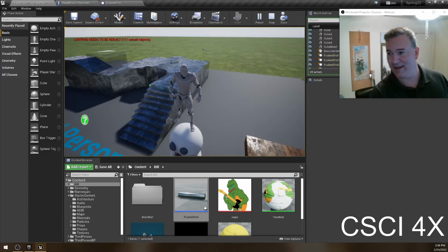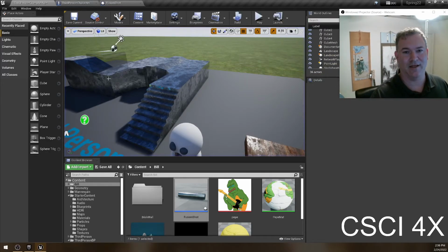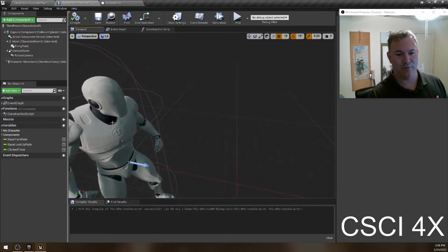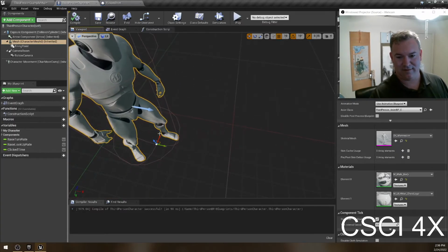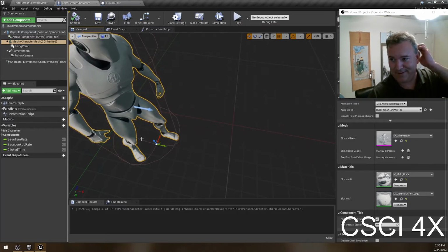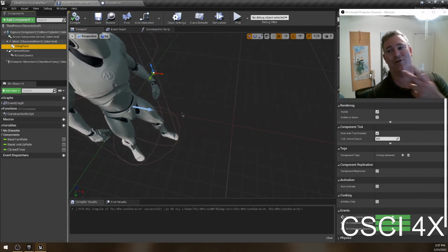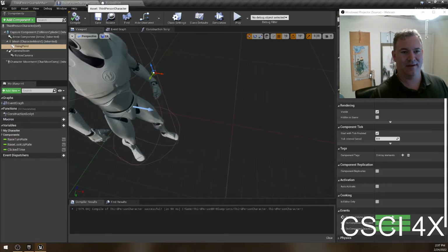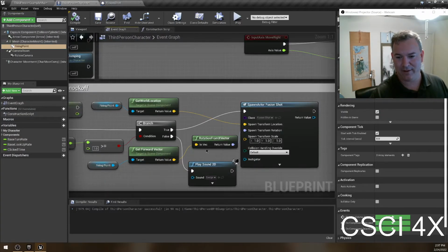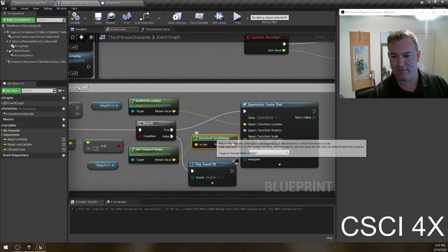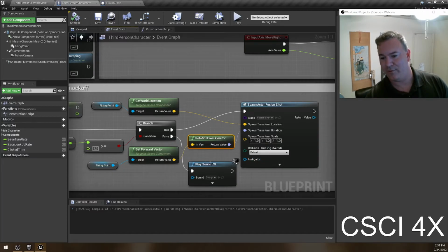And if you think this is the first time I've ever had shots come out sideways, like I said, it's a pretty common thing. The way you get the direction you're looking is you look at your viewport and see how the model itself is facing the wrong way. Just look at the red arrow. The red arrow is always your forward vector. That's why I rotated the firing point so that the red arrow is in the direction we're looking. Then I grabbed the forward vector out of the firing point and dragged that into the rotation transform, and it will do the conversion for you, this thing whose name I obviously cannot remember.